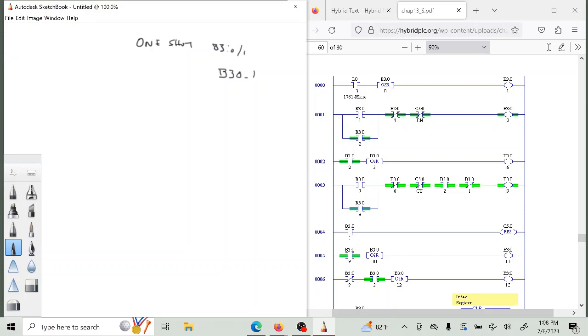We can go down to the second line, and we can just say use the input. If you're writing in Siemens, you can write the positive transition of the input for the start button. This would be my start button. And you would use that input with a memory bit as your blocking bit, and then you would come down here and you would have a seal on that.